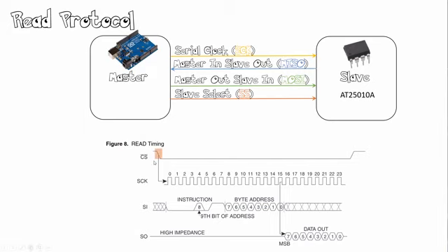Now in a similar way, we put our chip select down to 0 to activate our slave. We're clocking our device with a constant clock at a certain frequency, say around 10 megahertz, depending on the predefined speed of this chip. And then we send our instruction byte. Now this is standard for read or write. And then as you can see, we have a 1 and a 1, if you put this in line. A 1 and a 1 signifies a read.